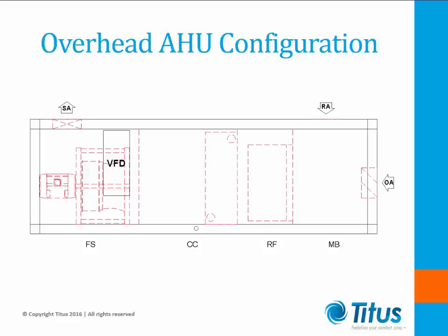Units can be controlled with primary duct static pressure resets per ASHRAE 90.1. In this configuration, the BMS will poll the configured terminal units and provide adequate static to maintain the minimum static required to meet capacity. The mixing box can be controlled as a simple static setting or provided with modulating dampers and actuators to allow demand control ventilation per ASHRAE 90.1. A mixing section with actuated dampers can also be used to provide a system with an air side economizer.